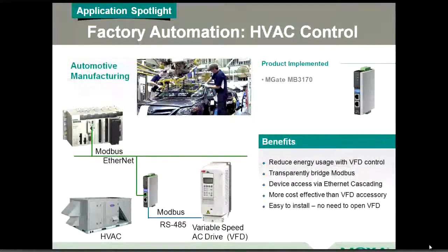So this had the existing HVAC systems with variable speed drives installed. Some of you folks that perhaps have experience working with variable speed drives, VFDs, inverters, a lot of these have, and almost all of these have Modbus built in with a communications port that's used for initial setup. All you need to do is plug into that Modbus port on RS-485, come in through a gateway, and now you're available on Ethernet.